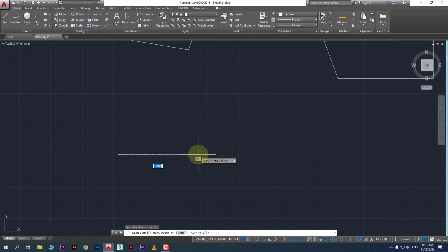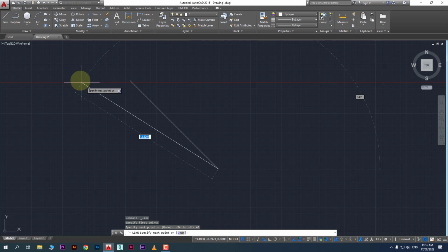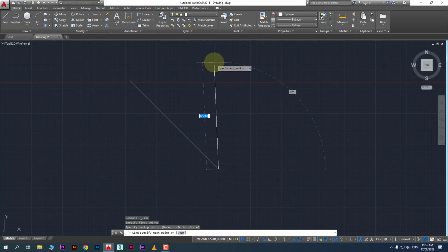The length is 10 units, for example. So here you will specify 10, the length. Now instead of clicking enter, press the tab key. When you press tab, you will see the length of the line will be locked and the cursor will move to another box which is for angle. So here you can specify angle 45. Then press enter. Now you see the line has been drawn at angle 45, because 180 and it will go down, it will also consider the same.